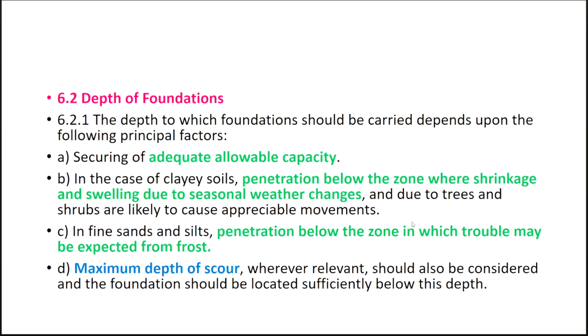In fine sands and silt, penetration below the zone in which trouble may be expected from the frost. Now in India, normally this is not there for the frost. Or the maximum depth of the scour, wherever relevant, should be considered. Now suppose you are having a building, you have any type of a stream or a nala just near to it, then it should go below the depth of the scour of that particular water stream.